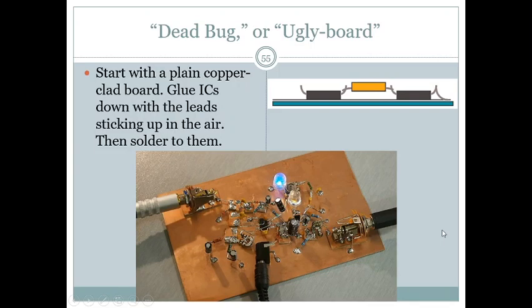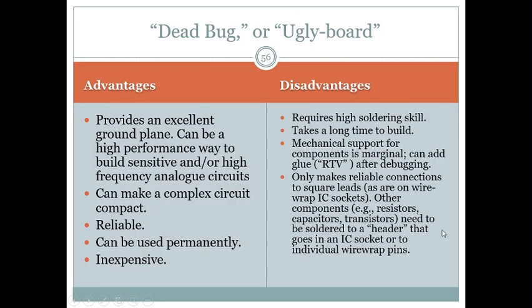One main benefit is you put everything on a copper board, which is a good shield and a good support. You can hold all the terminals that need to go to the negative onto the copper, which is made the ground. So it is very firm, soldered, but it doesn't look nice. Ugly. It's got its own benefits and disadvantages as well.